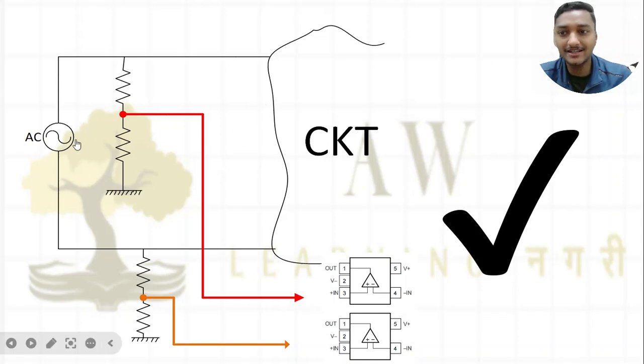So what is this circuit? Again, my AC main is there, which is connected to some sort of circuit. Now what I have done is that for phase I have connected two resistors with respect to ground, and then I have tapped in between. So I am getting here 0 to 3.3 volt. For neutral as well, I have added one more resistor divider circuit, with a higher value here and a lower value here, and then I have tapped between 0 to 3.3 volt.